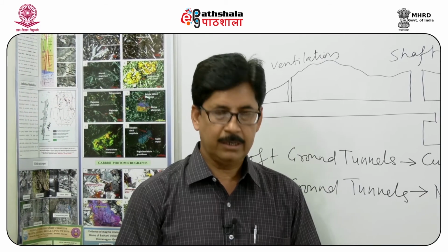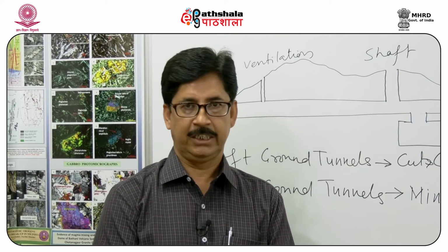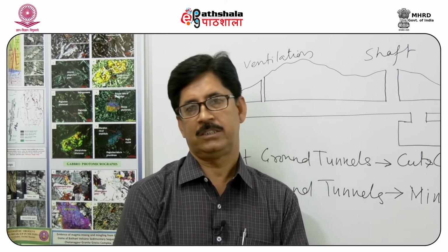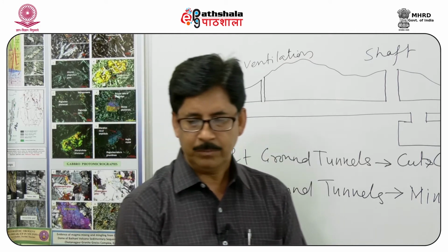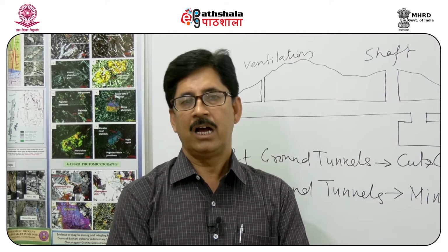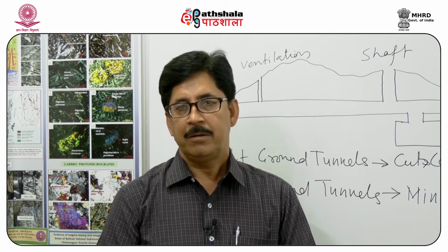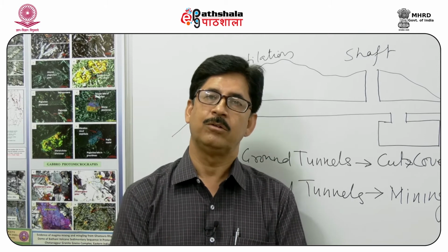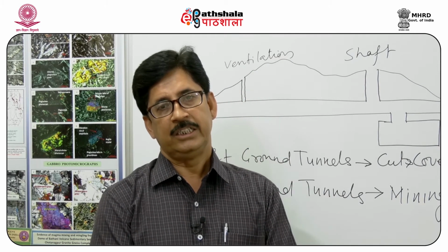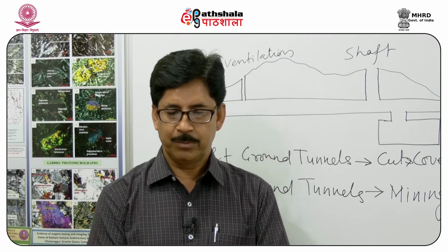This mining method is a very old traditional method, wherein rocks are excavated after drilling and blasting. There are different stages of this excavation, which starts from marking of the holes where drilling has to be done. After drilling, they are charged with explosives and the blast is carried out so that rocks are loosened. These rocks are excavated. The process of excavating rock is called mucking.